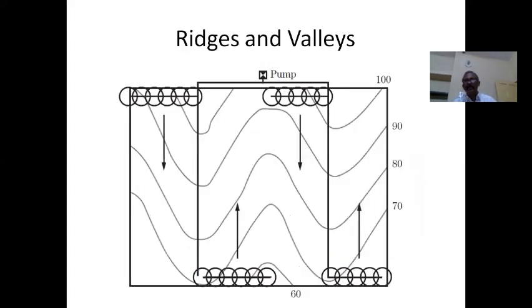See here, this is another situation in which you look at the contours first. Look at the values of the contours and their shape. See here, if you close this way, this is 100, 90. So this is a larger contour value at the center if you are closing something like this. So this is a ridge. This is a valley, and this is again a ridge. This is a ridge line.